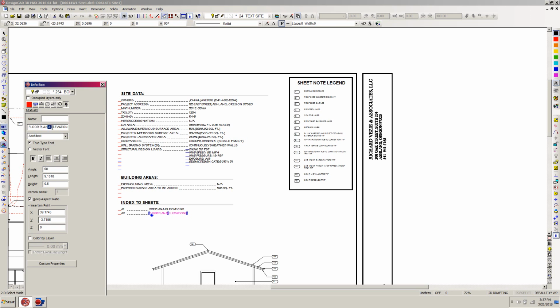So I'm going to select everything behind plan, and now I'm going to put a comma and a space, foundation plan, comma, roof framing plan, comma, wall bracing plan, comma, roof plan, comma, section A-A, and then the and sign, space, detail. So that's all in one line. It's going to be kind of long. I hit enter, and that's just a tad long.